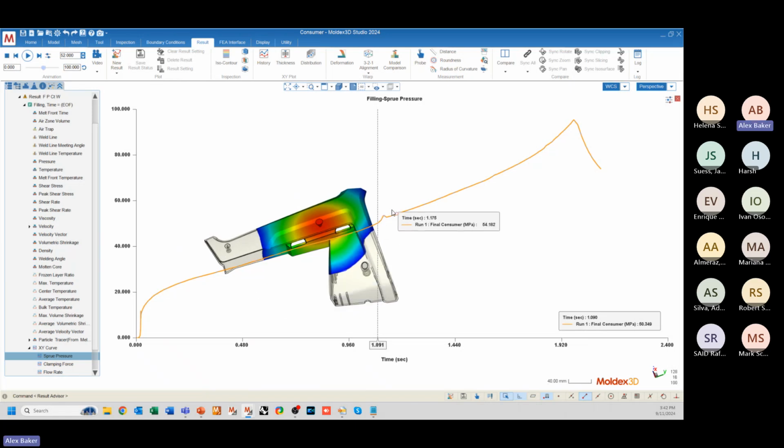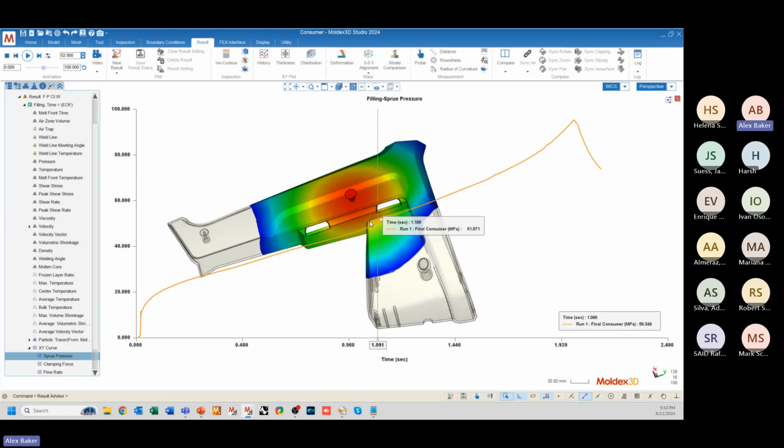And actually, in this case, the amplitude of this pressure spike is pretty low. Not really anything to worry about necessarily. It's just a little bump in the pressure requirement. However, if this pressure spike occurs closer to the end of fill or closer to this maximum pressure point, the amplitude will increase.